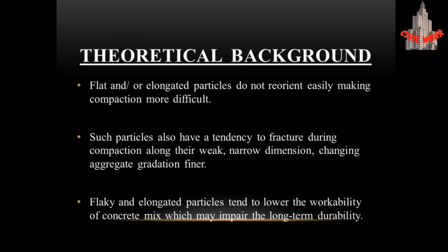Coming towards the theoretical background, flat or elongated particles do not reorient easily, making compaction more difficult. Such particles also have a tendency to fracture during compaction along their weak, narrow dimension, making the aggregate gradation finer. Flaky and elongated particles tend to lower the workability of the concrete mix, which may impair the long-term durability.